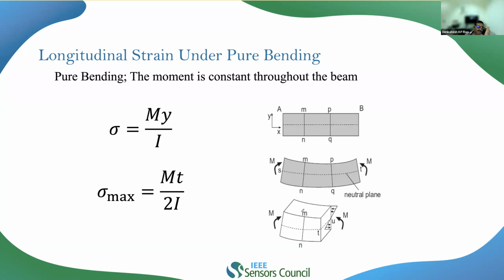So let us look into what will be the stresses induced in the beam. Whenever you take up a beam and apply a load on it, for example, a cantilever beam, if I take any cross section under consideration, we do have the moments on the respective cross section. This is one cross section I have taken. Whenever there are moments, the stress induced in the beam will be given by My by I, where M is the moment and y is the distance above the neutral fiber.